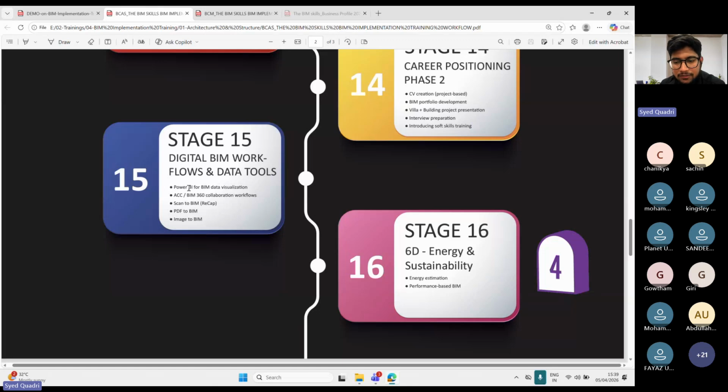And also we want to, for example, get the data from the model at different levels. What is the volume of concrete? So these are some scenarios to visualize the data. Now again, you are adding some dashboards. As I said, to check the model health, we should have one dashboard, and to do the clash detection, we should have one. So we can include that again.